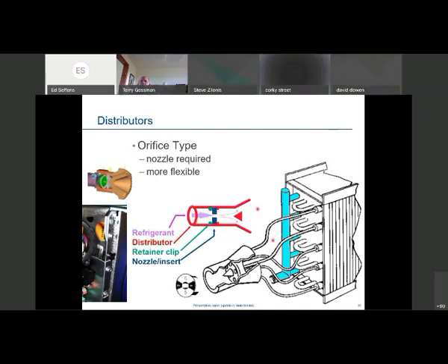And you see this style more common in refrigeration applications than I personally have with the Venturi, but they are out there. Now the pressure drop across this distributor assembly, along with the distributor tubes, is anywhere from a 25 to 35 pound pressure drop on this assembly right here, okay? And again, that's depending on what kind of refrigerant you're using. I believe ammonia is 35, and for the most part, everything else is pretty much around 25. But at any rate, if you have any questions, you can refer to the literature that's provided.